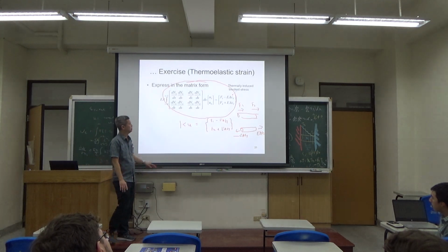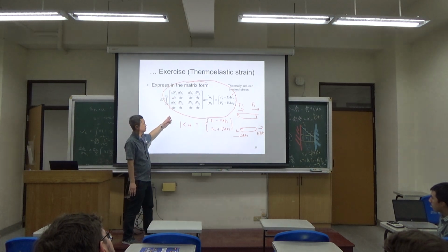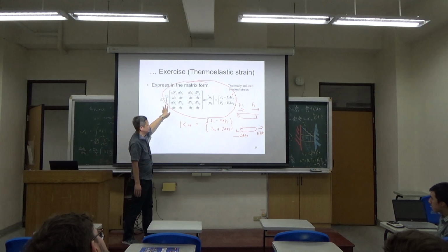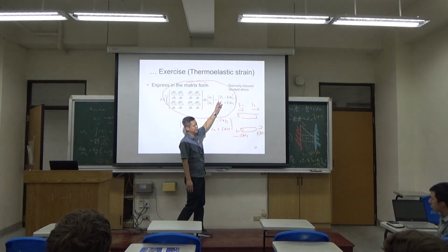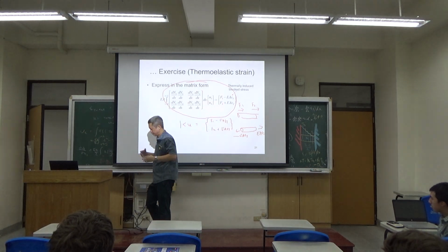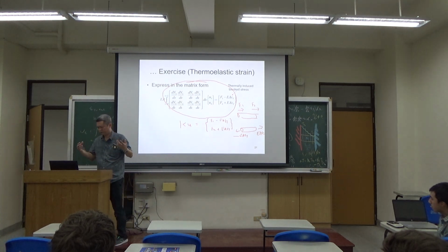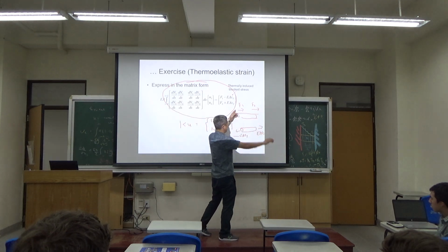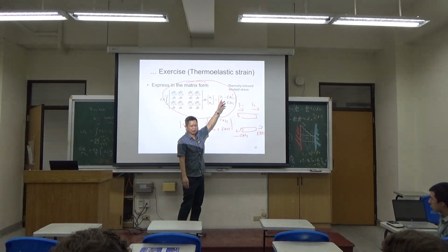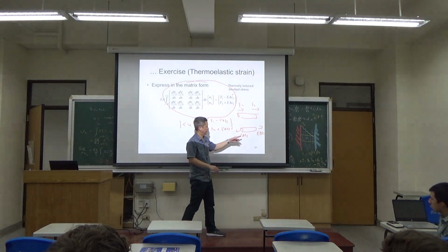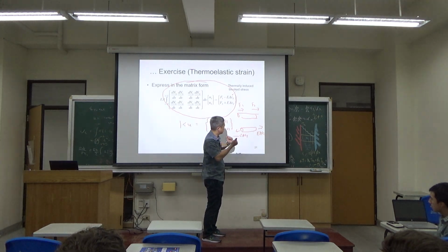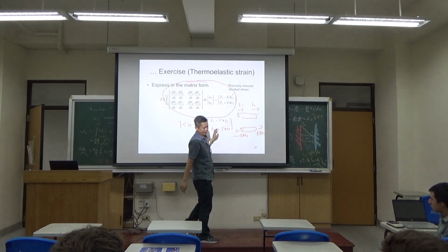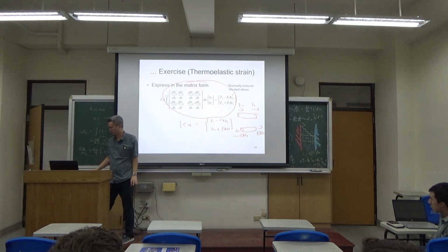So with this, if you are using the Galerkin method, you're still going to obtain the same expression for the stiffness matrix times displacement vector. The right hand side consists of 2 parts. One is the pure mechanical force F1, F2, which is defined to be positive toward the right. But the thermally induced force is imposing a tension, so they are positive on the right, negative on the left. So this is what we do.